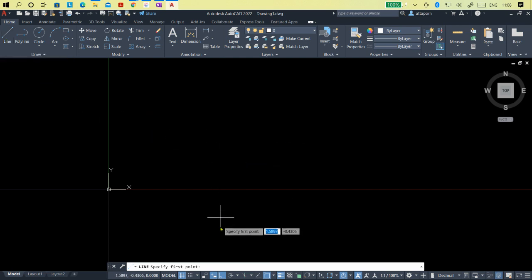and then you see here, dynamic inputs. They ask you, maybe you are seeing this moving, to specify the first point, and you can input the coordinates x and y. You press 0. This one is x. So if you want to press y, you press tab, 0. The tab on your keyboard is this. Maybe you swap x and y.